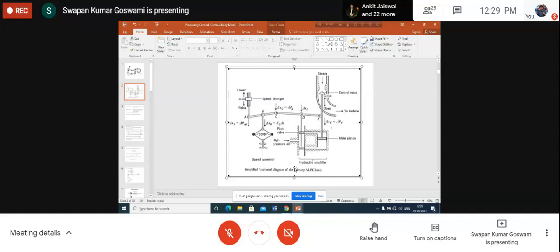Active power, if we want to increase active power, then we have to increase the delta angle. That means power angle, sine delta should be increased, and delta will be increased when the angle between EF and VT increases. When EF and VT are synchronous, previously they are at alpha, then synchronous.